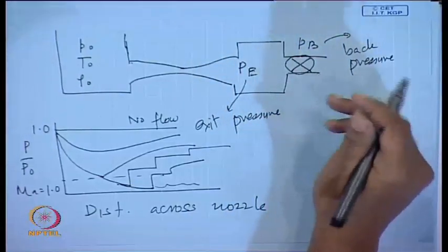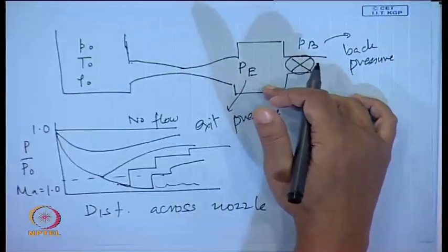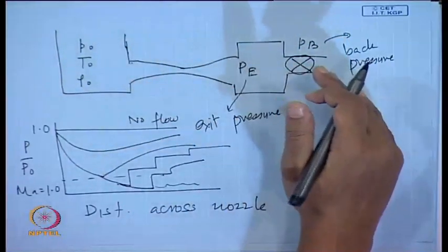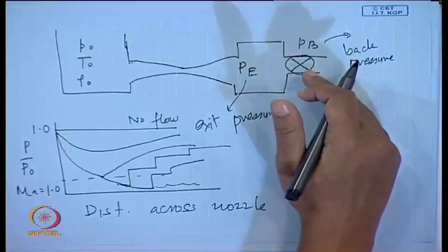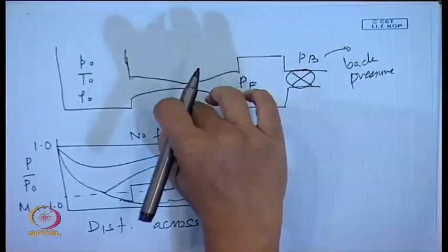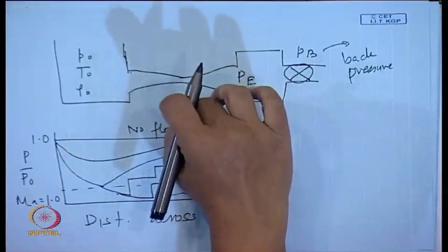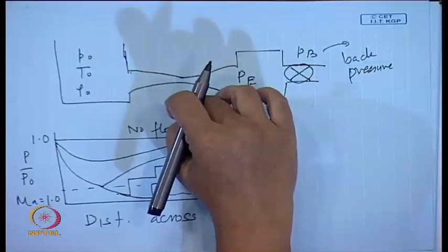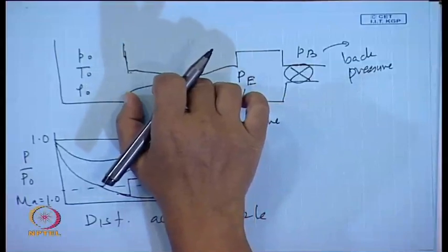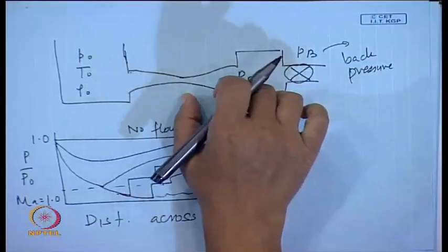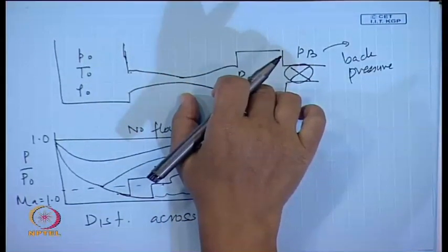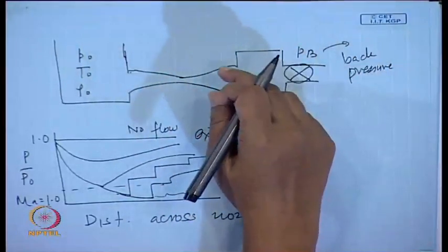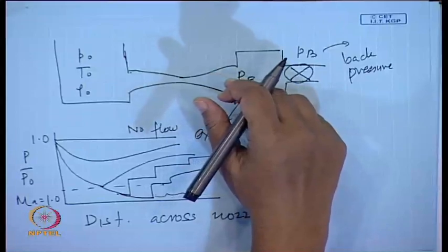Okay. So, the same thing happens, but in this particular case we can go from the subsonic to the supersonic zone, but that too only till a particular point when choked flow conditions have been reached. The moment choked flow conditions are reached in the neck region, we cannot do anything more. Although the flow in the upstream region is not affected, in the downstream region we find normal shocks, and these shocks start propagating and the flow rate cannot be increased any further.